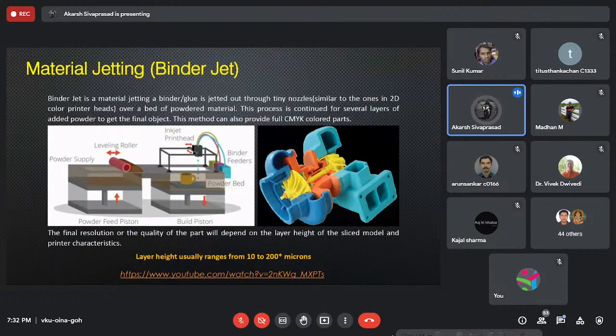You replace that cartridge with a box of glue, and you have an extremely thin layer of powder, roughly 15 microns thick, uniformly spread out. The inkjet can raster and put the binder droplets wherever it needs, and then the next layer can continue. The next layer brings the powder from a reservoir station, and using a doctor roller, it slides the powder over the previous powder layer.